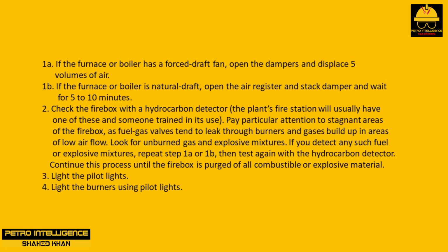1A. If the furnace or boiler has a forced draft fan, open the dampers and displace 5 volumes of air. 1B. If the furnace or boiler is natural draft, open the air register and stack damper and wait for 5 to 10 minutes. 2. Check the firebox with a hydrocarbon detector. The plant's fire station will usually have one of these and someone trained in its use. Pay particular attention to stagnant areas of the firebox, as fuel gas valves tend to leak through burners and gases build up in areas of low airflow.